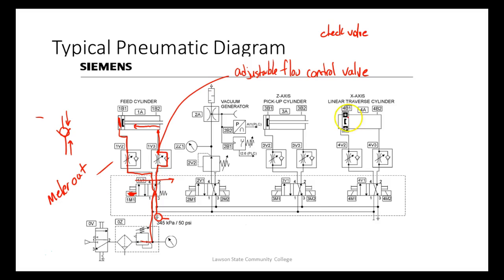Now this guy right here, guys, this is a symbol of a magnet. If you remember, that's a symbol of a magnetic... oops, sorry, wrong symbol, thinking wrong. So if I've got a symbol of a sensor, right, we come up here and put this, then we come down here and put some type of symbol. If we put this at the bottom, it means it senses a magnetic field. So what this means is this cylinder has a magnet in it. It's mounted on the piston itself.